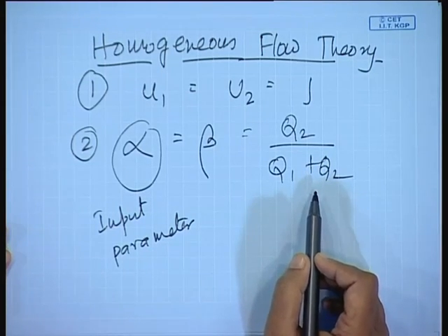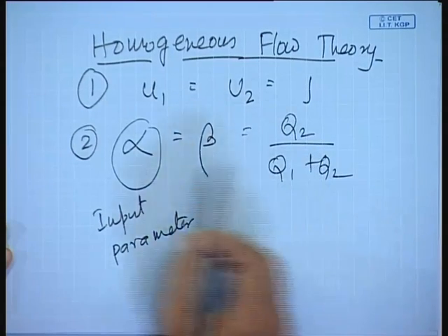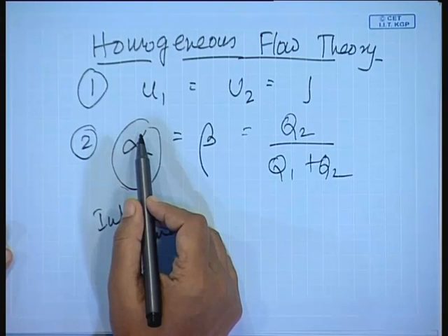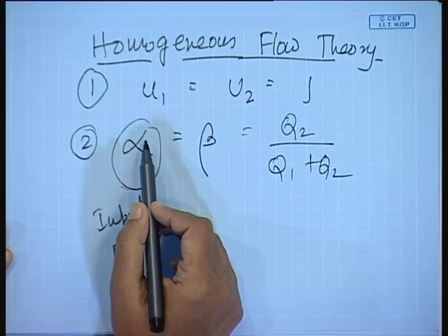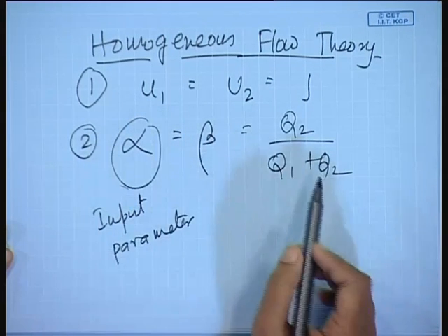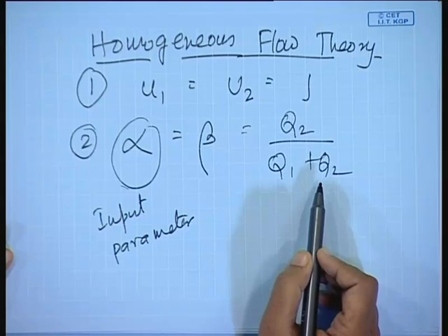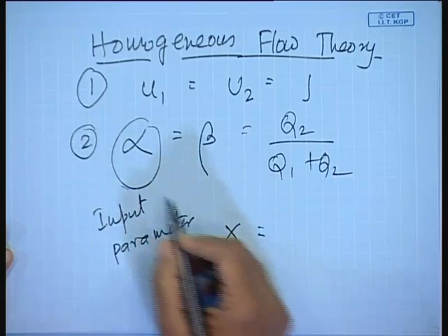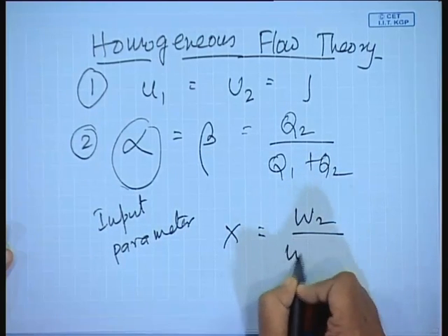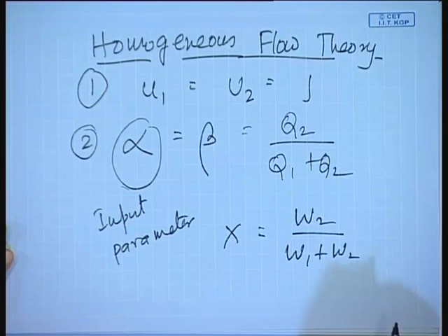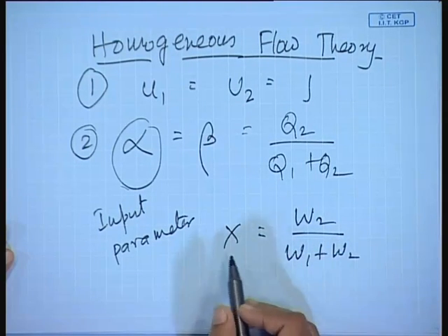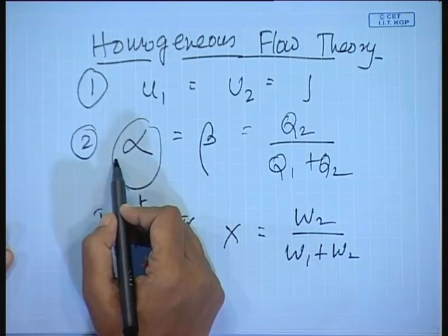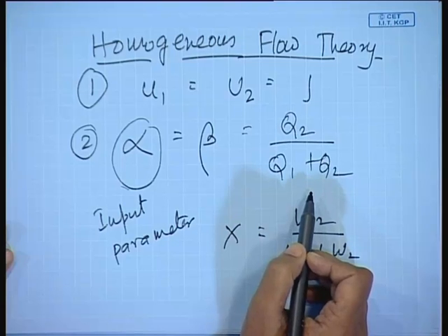This has given us that the inlet void fraction and the in situ void fraction have become equal, or in other words, the void fraction or the in situ composition is nothing but a measurable parameter. Just for recapitulation, suppose there is evaporation, condensation or boiling, then we can obtain the quality from the inlet mass fraction, and the void fraction from the inlet volumetric flow rate.